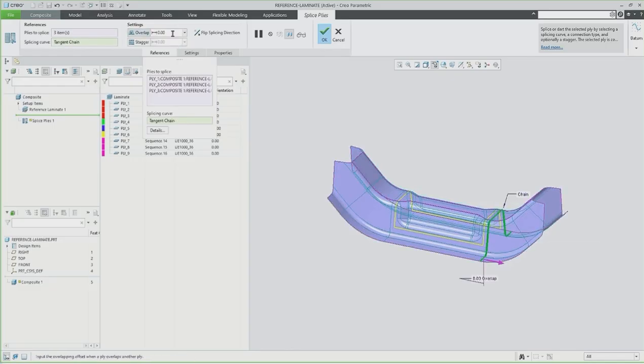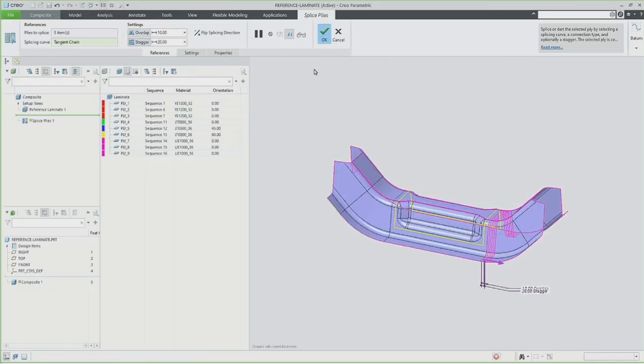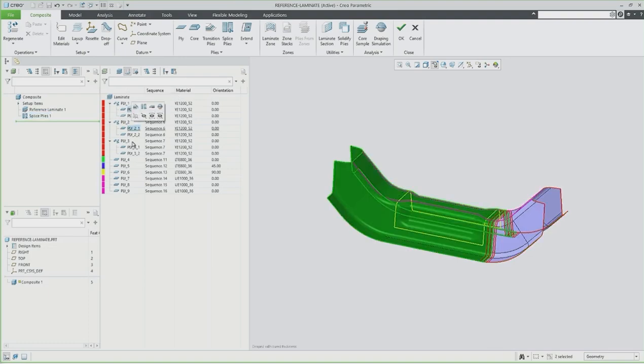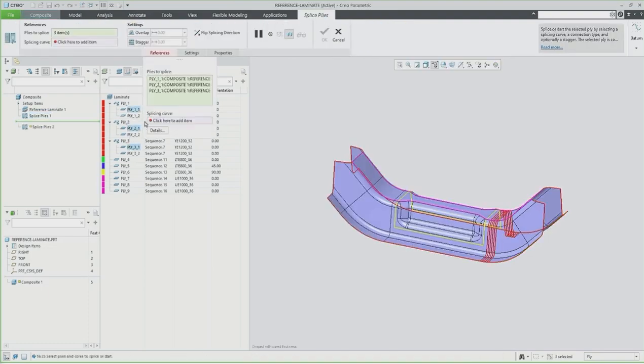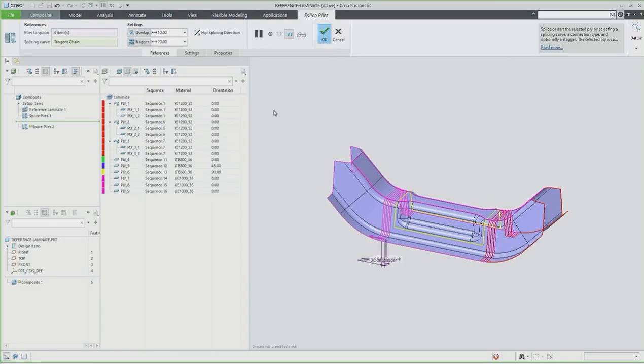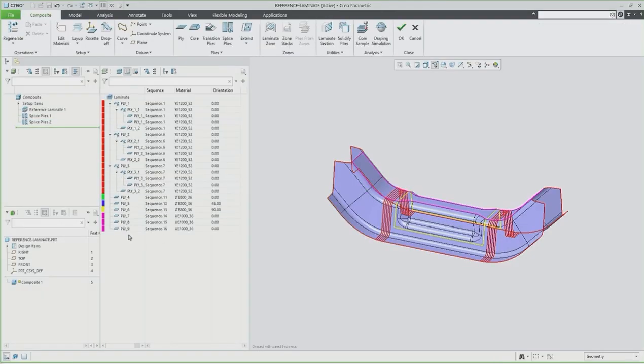time. Creo 12 also sees the introduction of a laminate reference model following the same concept as a manufacturing reference model, where the design part would be inherited from the manufacturing part, such that the manufacturing changes could be applied without changing the design model. For example, a casting model is different to the finished design part.